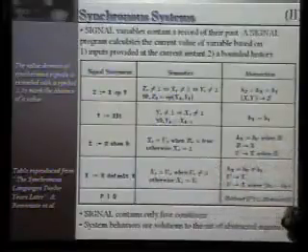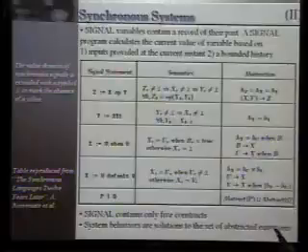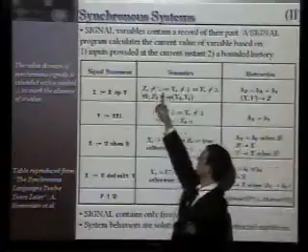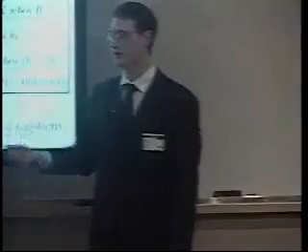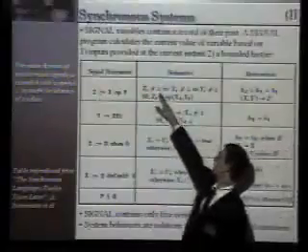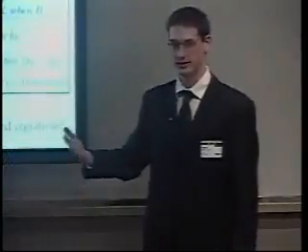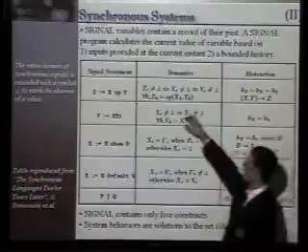Now the trickier thing is that when a system gets hit with some events, not all of them might be there. Some might be missing. And what all of these synchronous languages do is they extend the values that a variable can take with something called absent. And it's represented with this bottom symbol here. And absent means that there's no value. At this point in time, the system was not given input on that particular line.